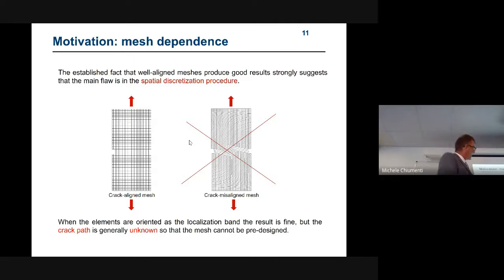But if instead of this mesh, you decide to use, the accuracy of the projector is not very good, but this is a mesh which is slanted like this, okay? So exactly the same boundary condition, exactly the same material, everything the same. I'm just changing the meshing, and this is the result that you obtain. So just changing the mesh, the solution is rubbish.